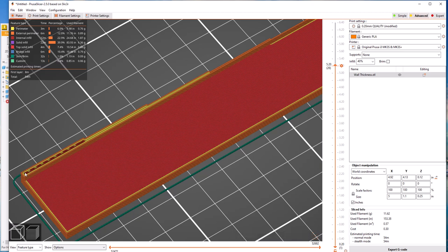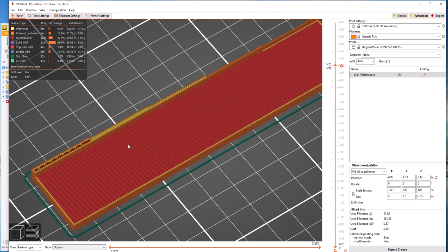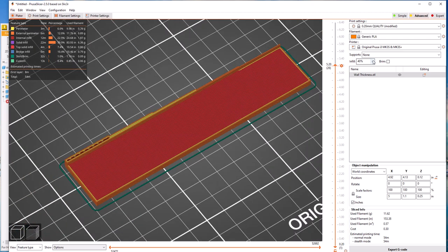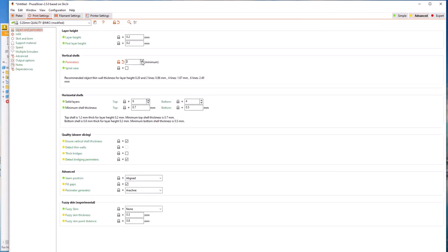So if your wall doesn't have to be a 1/4 inch thick, maybe you think about bringing that wall thickness down. I think an 80 thou to 100 thou wall thickness is pretty good. 80 thou here is this one, and it's not putting any infill in there. It's going to be strong for what you're doing, saving material and not putting any infill in there. Not that you can't, but just thinking about design for wall thicknesses. So I'm going to go back down to 15%. I'm going to come back over here and go to a 3%.